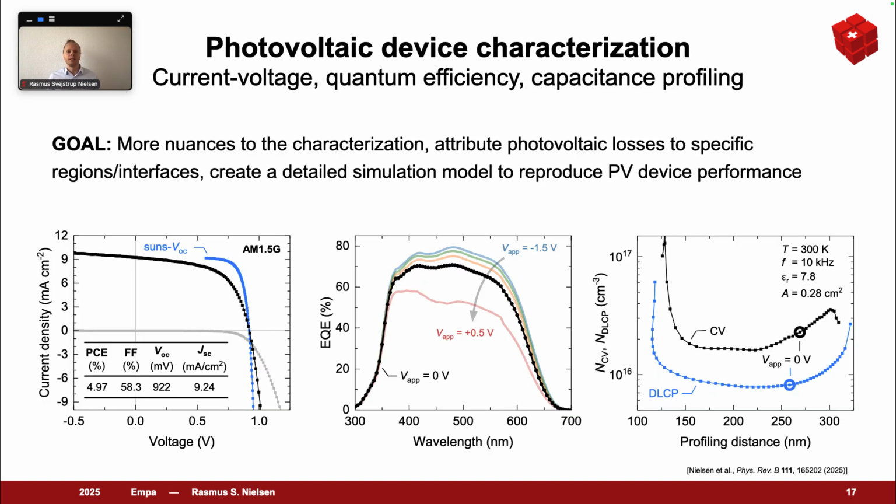The photo-absorbing layer of this selenium solar cell was actually fabricated in parallel with the Hall bar. Now, as the main surprise from the photo Hall experiment was a very low dark carrier density, we decided to investigate the width of the space charge region using voltage-biased EQE as well as capacitance-based techniques. Now, had the intrinsic carrier concentration actually been on the order of 10 to the power of 12 per centimeter cubed, then the space charge region under short circuit conditions should be on the order of tens of microns.